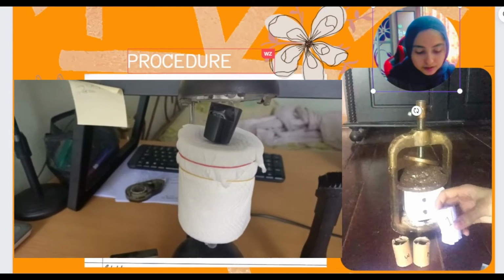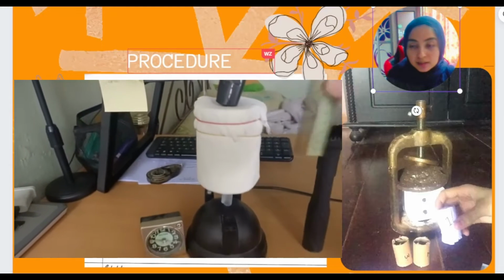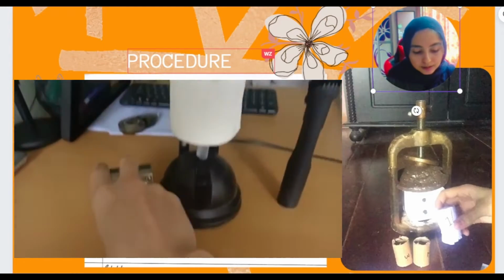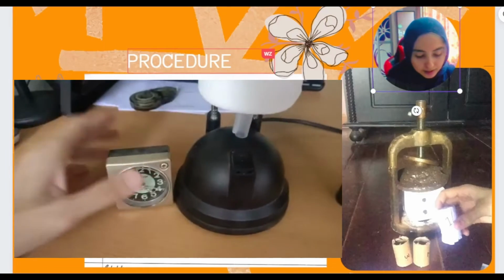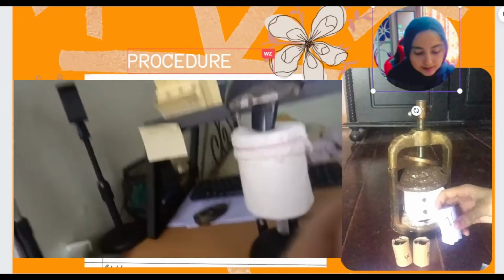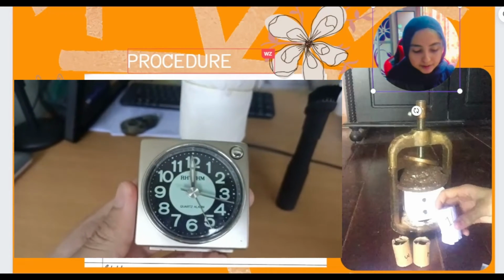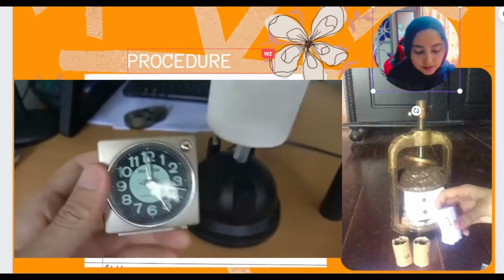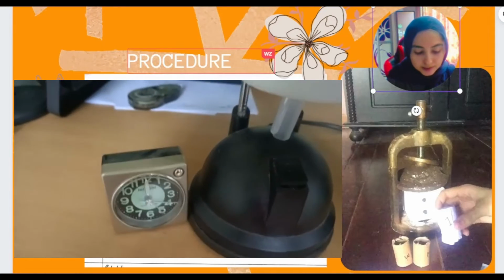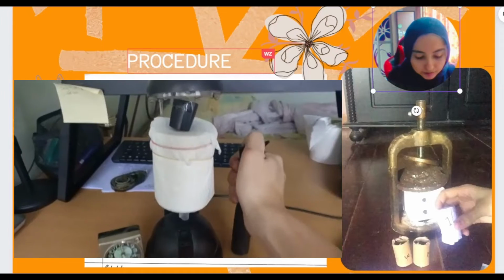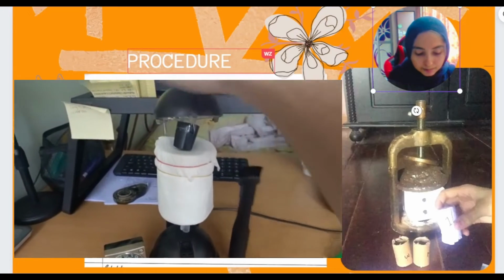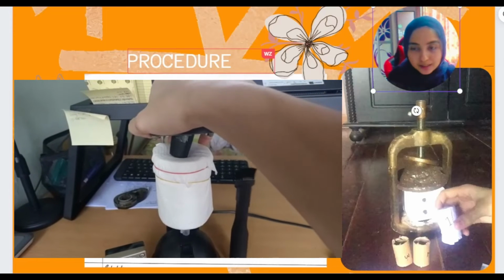The tolerance is plus minus 2%. Later, the scale meter at load applied is set to zero. Then, the load is applied to the core sample with steady increments and the failure load P is recorded.